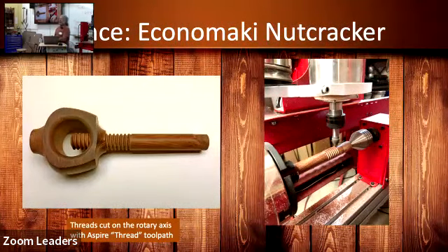This is what Vince did with his rotary axis. Remember we said there's that thread toolpath? Here it is in action. This isn't the VCarve thread, this is a legacy thread. Conversational CAM, where I both cut it to round and then did the threading and cut the body for this part. And I had a tap that I used to cut the inside thread.